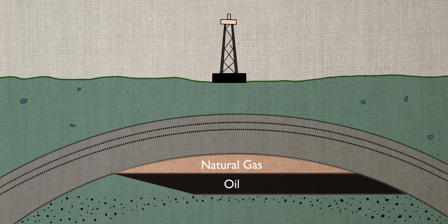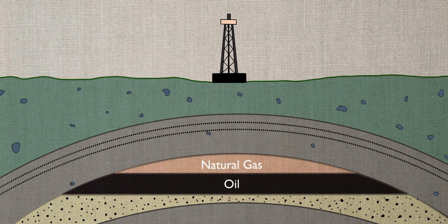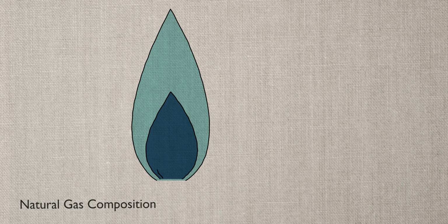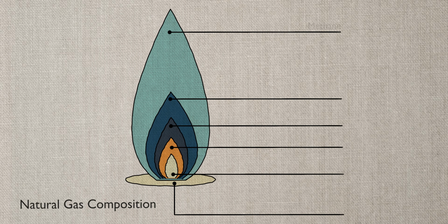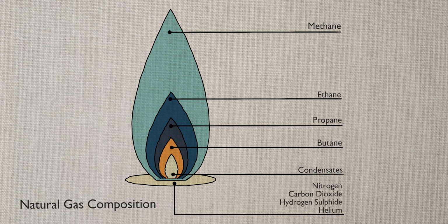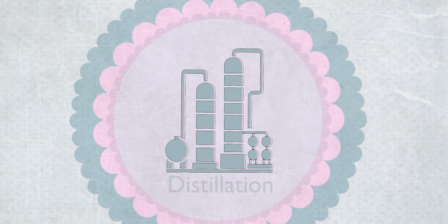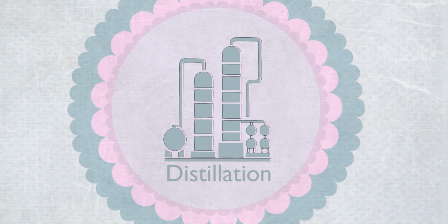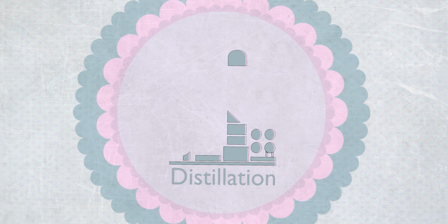Helium is usually produced as a byproduct of natural gas processing. Natural gas contains methane and other hydrocarbons, which are the principal source of heat energy when natural gas is burned. Most natural gas deposits also contain smaller quantities of nitrogen, water vapor, carbon dioxide, helium, and other non-combustible materials. When the gas contains more than about 0.4% helium by volume, a cryogenic distillation method is often used in order to recover the helium content.